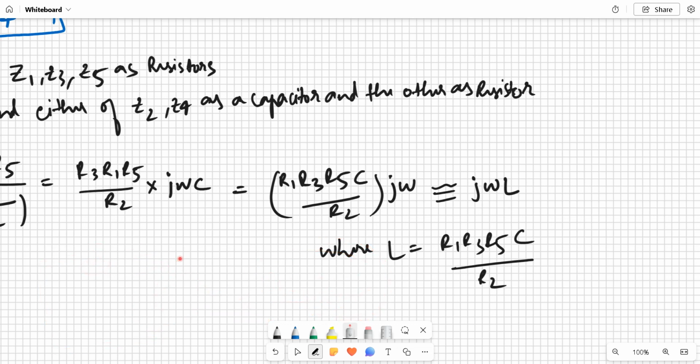As mentioned earlier, we can not only simulate basic passive components, that is resistance, capacitance and inductance, we can also use second order impedances. In Bode plots you might have seen, if there is an s square term in the denominator, the Bode plot will roll off by 40 dB per decade. And if the numerator has an s square term, then the Bode plot will rise with a slope of 40 dB per decade. That is the basic functionality of this impedance converter.